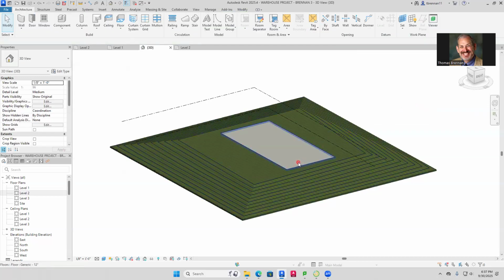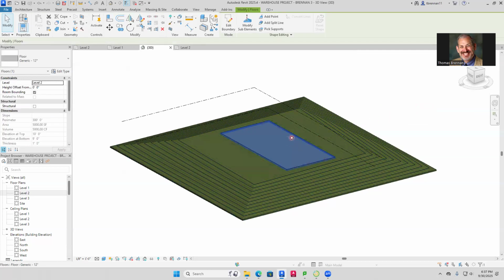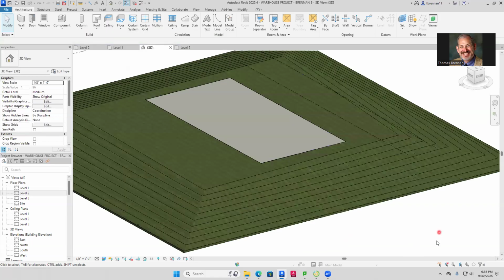And then we could actually make this a little bit higher, so it's kind of like a flat on a flat surface. So what we're going to do right now, we're going to click on this and make it 1 inch above. We'll go over here, the height offset. Make sure you type in the inch, 1 inch. Inch is the double quote, and you hit enter, and you're going to see it push up just a little bit. So it's got a little bit of an edge there. And that is how you would go ahead and put this together.